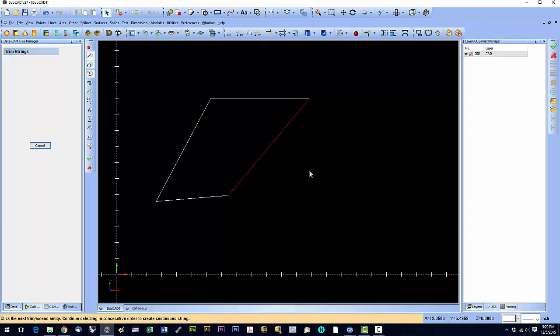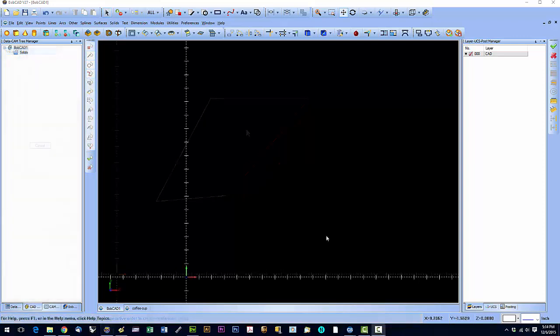And that's basic trimming. Again, very important that when you draw something for plasma cutting to go into SheetCam, that it be a closed contour, and trimming is an excellent way to ensure that you have closed contours. Also keep in mind when trimming that the trim tool is actually called the trim extend tool. So it kind of works both ways.